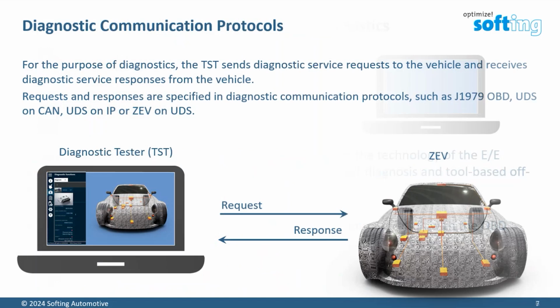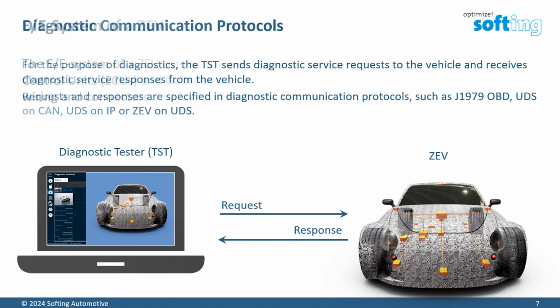Diagnostic communication, what does that mean? For the purpose of diagnostics, the tester, TST, sends diagnostic service requests to the vehicle and receives diagnostic service responses from the vehicle. Those requests and responses are specified in diagnostic communication protocols, for example, J1979, that's OBD, UDS, Unified Diagnostic Services on CAN or on IP, and the brand new one, ZEV on UDS, Zero Emission Vehicle on UDS. Keep in mind requests and responses.